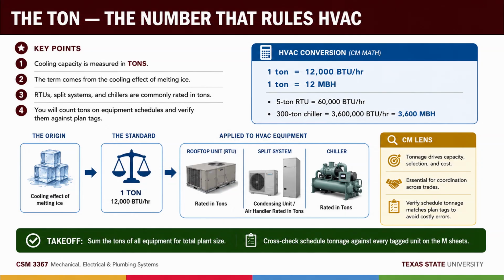That's the whole trick. A roof might carry a CLTD of 40, 50, 60 degrees at peak while the plain air-to-air difference is only 20, which tells you the sun can be doing 2/3 of the work. Run one on the board so it's concrete. A 10,000 square foot roof, insulated to R25, so U is 1 over 25, 0.04. Plain air-to-air delta T, 95 outside against 75 inside, 20 degrees. Naive math, 0.04 times 10,000 times 20, 8,000 BTUs per hour.